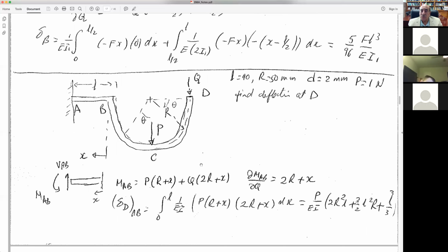So it makes more additional terms. If you look in the book, there's more energy stored in these components. But for practical purposes, we deal with problems that have small cross sections in relationship to the radius, so they look like wire mainly. And in these types of problems, we can safely ignore the energy in shear and axial, and the energy stored in bending is the majority, maybe 90%. And this is the type of problem that we have.